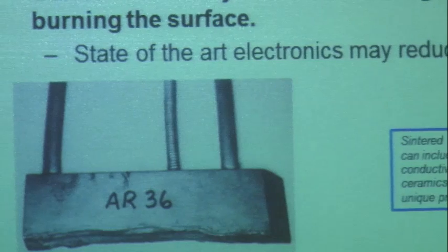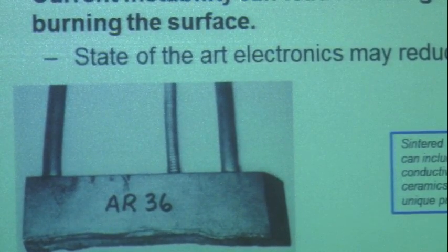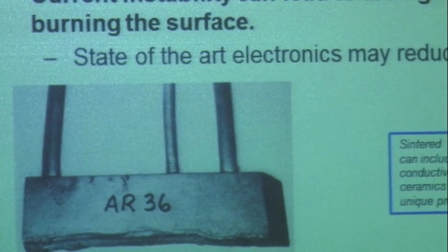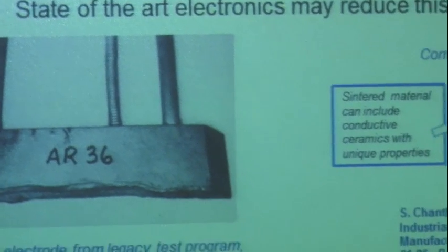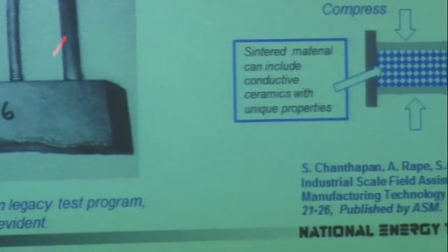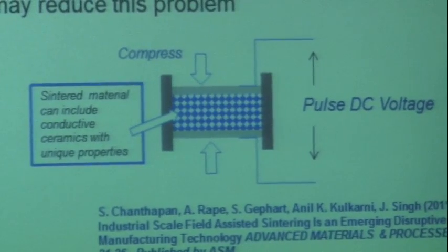But it's not just cooling that surface. If you did this, for example, with coal, then you've got to worry about chemical attack, right? Because you have all the coal ash at those very high temperatures, and you've got to worry about electrical attack from arcing, focusing energy down into the electrode surface itself.